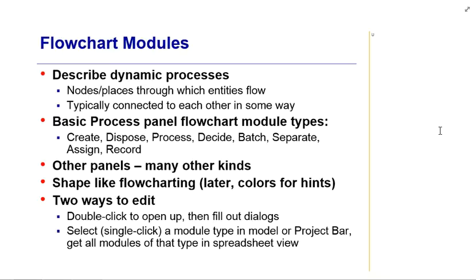But value stream mapping, just to sort of introduce it a little bit here, is basically a flow chart that you create of a process, and it could be any kind of process. It could be the drilling, heat treating process I just described. And it's a visual. It shows each process, shows the flow between processes. The value stream part of it comes in as you look at each process and look for value added, and you classify things as either being value added or non-value added. So an example would be in our previous process, the heat treat would be value added, the drilling would be value added. The process of batching the parts, physically moving the parts, is not value added.